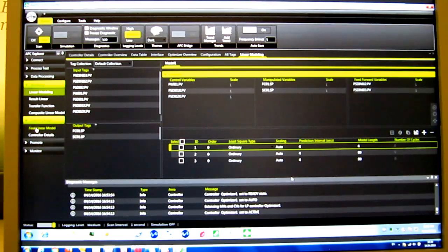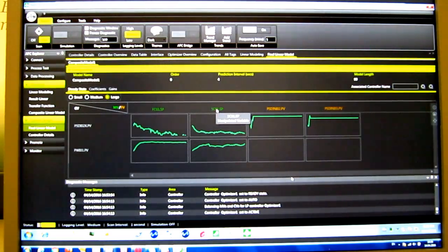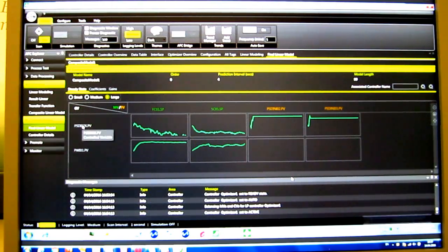You can see this is my manipulated variables, here's my feed, here's the speed, and this is the shape of the curve for the particle size distribution and for the power. So you can see here, if I do an increase here, I'll get an increase here in power. Does this answer your question? Yes, it is showing actually the matrix of the controller, the connection between parameters, how the manipulated variable affects the control variable.